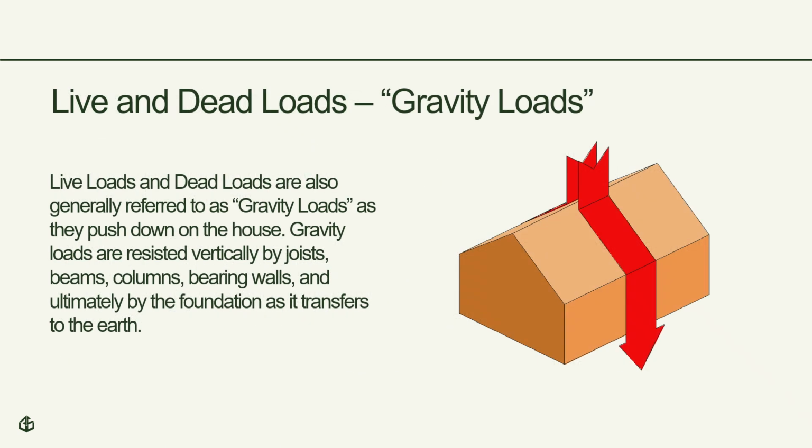Live loads and dead loads are also commonly referred to as gravity loads, as they push down on the house. Gravity loads are resisted vertically by joists, beams, columns, bearing walls, and ultimately by the foundation, as it transfers all of that load down to the earth.